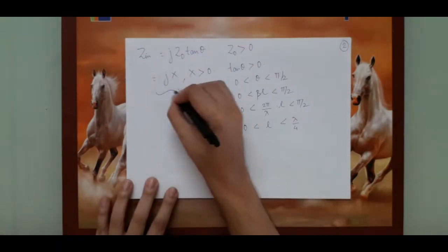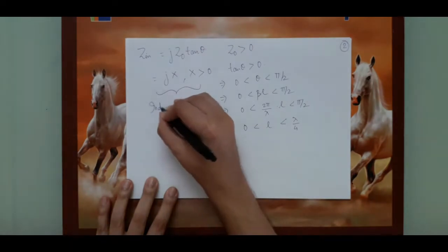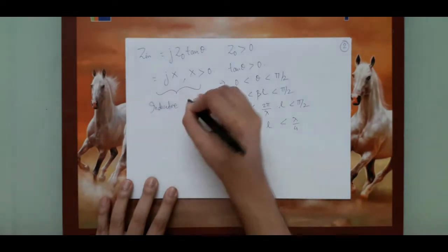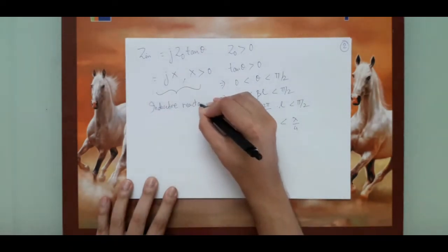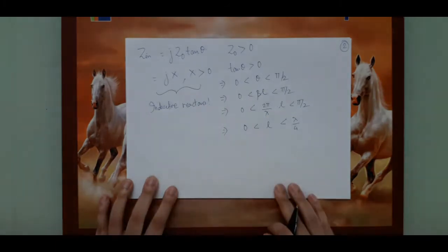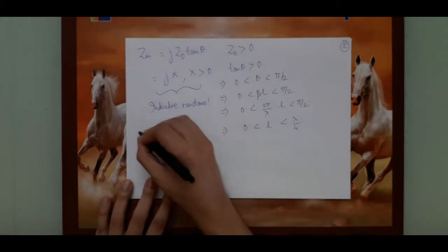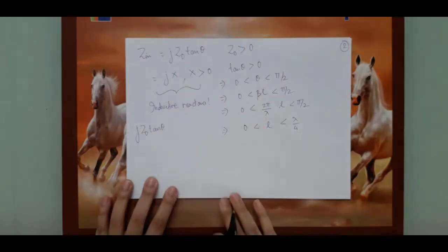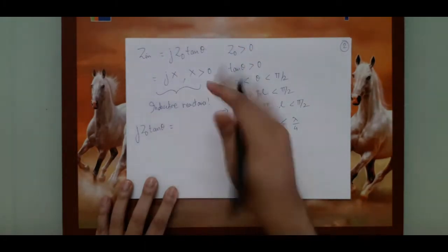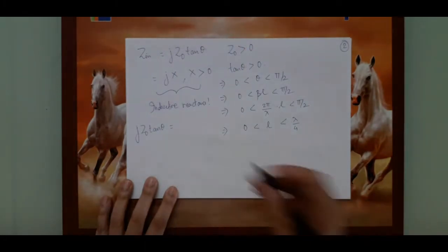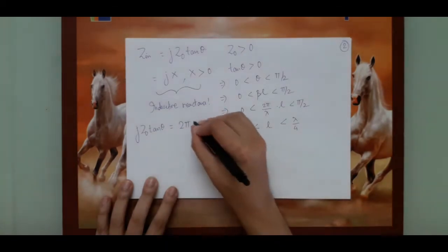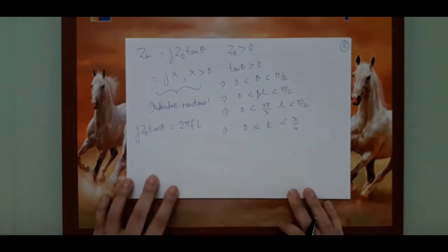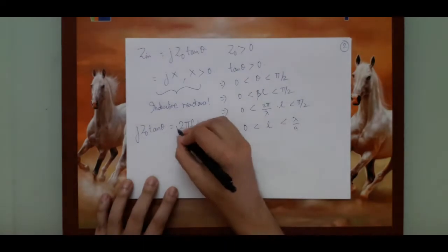So this is very similar to inductive reactance. So I can say this JZ0 tan theta, or this positive quantity, is equal to some inductive reactance of some inductor, which is nothing but 2 pi FL, where L is the equivalent inductance.